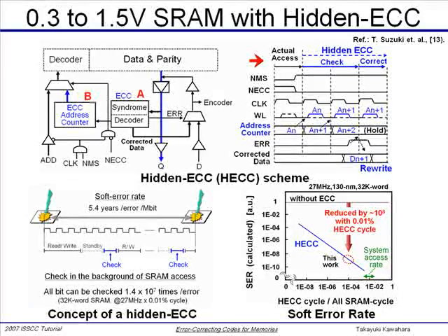But when some memory blocks are not selected, the hidden ECC can start to work. This SRAM has its own address counter for ECC. When there is one block that activates, the ECC is asserted. Then in the background, the ECC suppression is running.